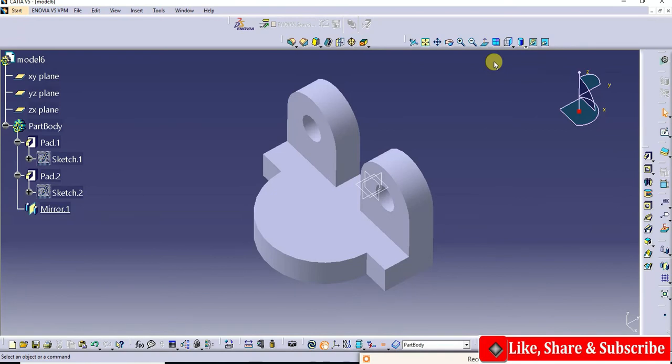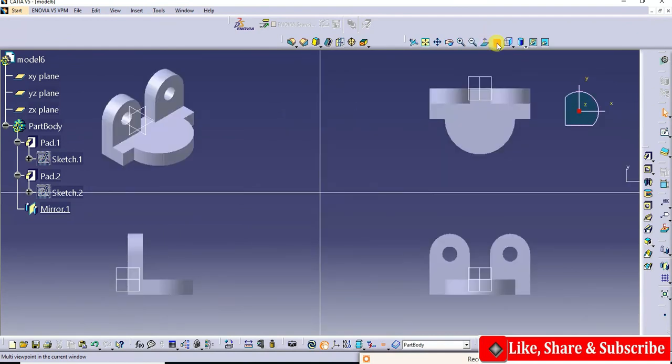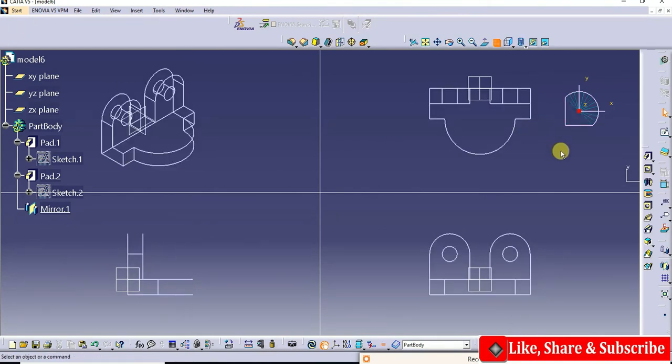Now if you want to see the various views, there is a command called create multi-view. Now I'll select wireframe here. You can compare, this is an isometric view, this is a top view, this is a front view, this is a side view.